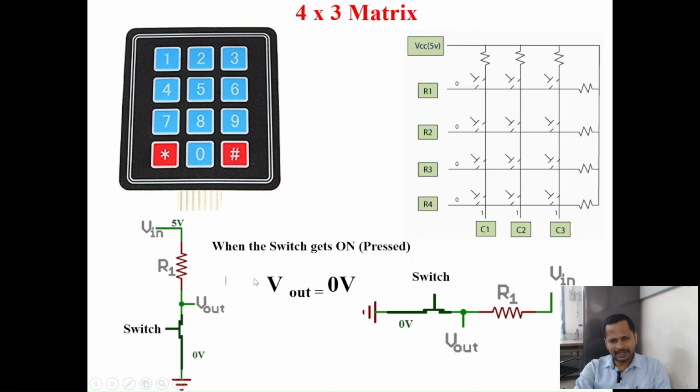So through this logic high and logic low only, any processor or controller is going to recognize the status of the input and output device. So if I have the internal pull-up resistance, this is going to be the result. That means that the pull-up resistance may be internal or external. So by default the data bus is going to carry the voltage high.